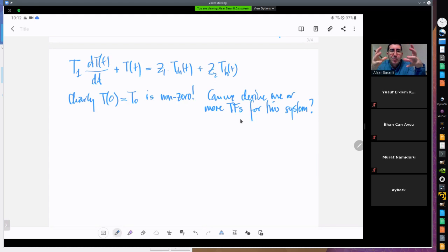In superposition, remember from circuit theory, you basically kill the sources one by one. Here we have two inputs. We will assume one of the inputs to be 0, and derive a transfer function from the other non-zero input to the output. We will then kill this input and make the other input non-zero, and derive another transfer function from that input to the output.